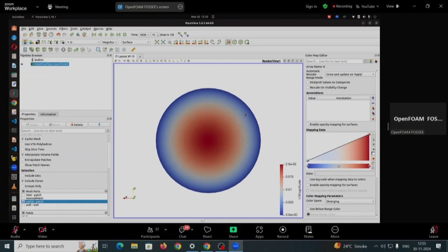If I do rho A V, like Q, the volumetric flux will be highest at the center and lowest at the wall. But if I look at the temperature, it is the other way around, right? So if I do just a patch average, it will mathematically average and give equal weightage to all the cells, and that is not an accurate representation. Whenever you want to do that, you need to do something like rho A V and then into T.